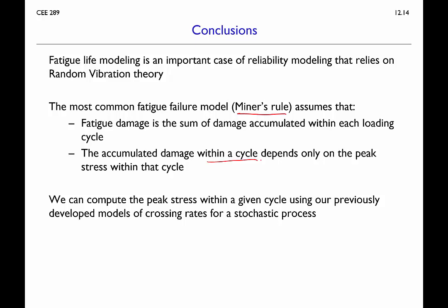Those form the basis for things like simple design rules. In other situations where there's some nonlinearity, you can get a bound on your answer, and so that's still relatively informative. Ultimately, since these things are all empirically calibrated, even if the theory doesn't perfectly match up with the circumstances it's being applied to, we can make up for that in some kind of empirical calibration of the coefficients for the model, and it still motivates the functional forms of these models, and those functional forms seem to be quite robust in a lot of circumstances. So it gives us some confidence that we understand a little bit what's going on, albeit with some assumptions, but it seems to be a reasonable model for the world under these high cycle fatigue cases.